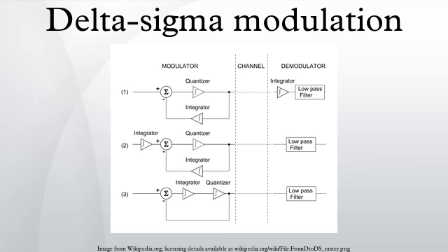Eventually Van goes to zero which means that the current sum goes fully negative and the integral ramps up. It shortly thereafter crosses the threshold and this in turn is followed by Q, thus switching the impulse current off. The capacitor current is now zero and so the integral slope is zero, remaining constant at the value it had acquired at the end of the impulse. The count stream is generated by gating the negated clock with Q to produce this waveform.